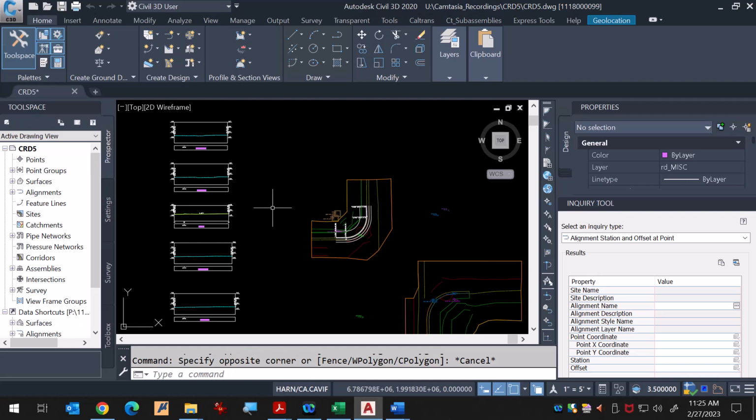In this video, we're going to be creating all of the cross-section alignments that you'll need moving forward. For example, we'll create the cross-section at our begin-end construction lines. We'll also create the BC and EC cross-sections, and we're going to be creating the begin and end landing lines, just tentative ones. And then I think in this video, we're going to be creating the back of sidewalk and the T-curb and back curb as well.